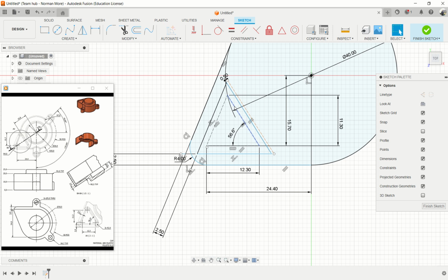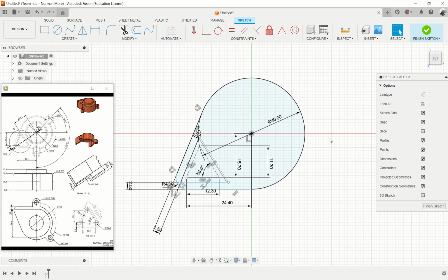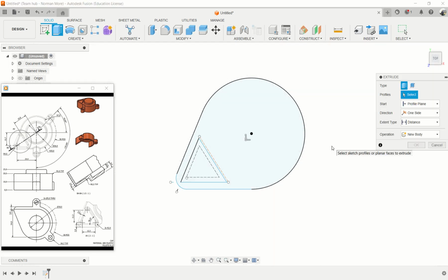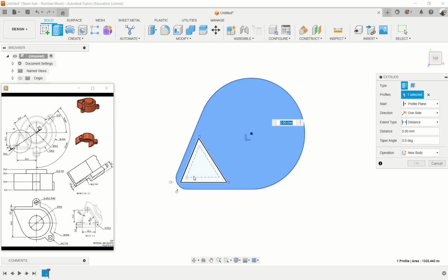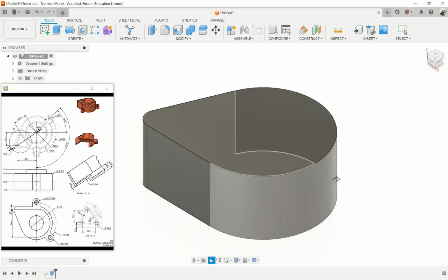We can put fillets all around, or maybe do it, let's do it after I've done the extrusion. So we're going to use this sketch twice. I'll do E for extrusion, and then I'm going to extrude that. I click on both because I want all of it to be extruded, and by that height there, 20 millimeters. So I put in 20 and enter. So now that will be the first.